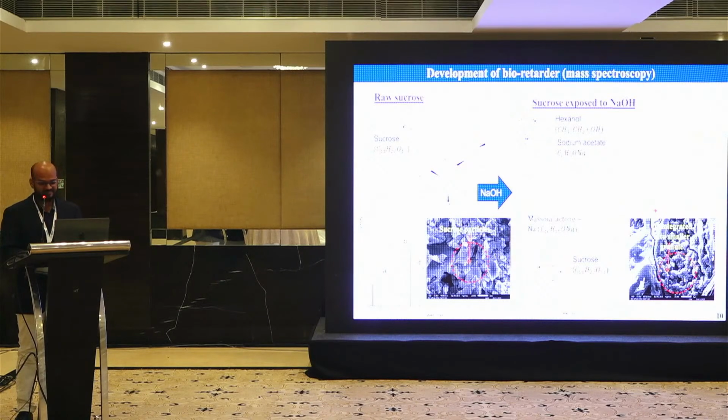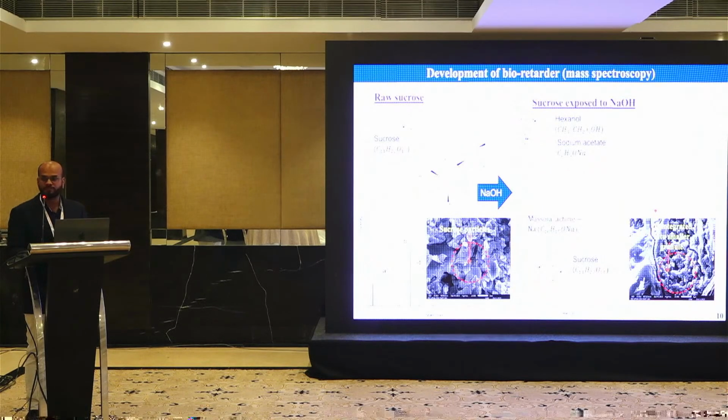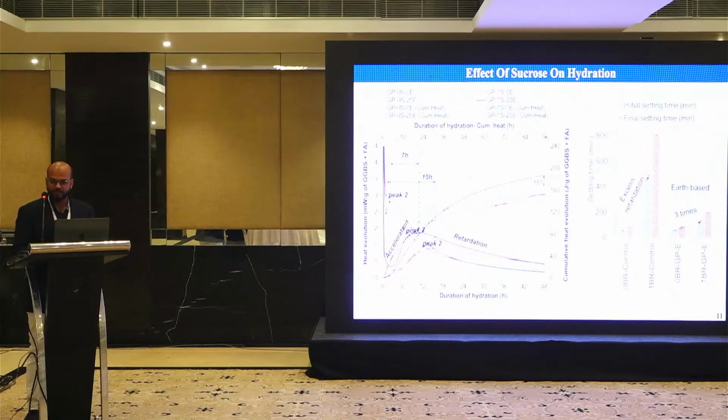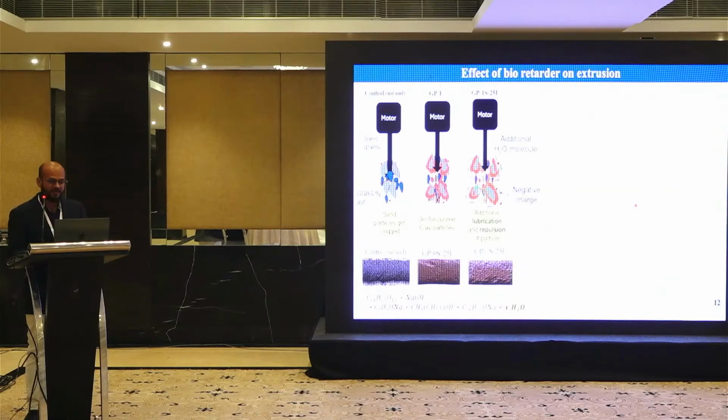Okay sir. So further we have improved the 3D printability with one bio-retarder, that is sucrose, to extend the 3D printing time. The open printing time was improved by 8 to 9 times. What is the science behind the improvement in 3D printable time and the quality of extrusion?